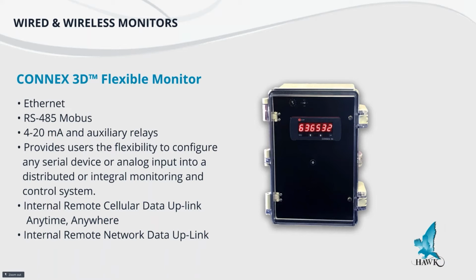That all sounds very technical and sophisticated, but it basically is just a data highway, with Modbus being the language that we communicate within that data highway. It allows us to communicate with many other devices, whether they be 4 to 20 milliamp analog devices, or 0 to 10 volt analog devices, or whether they just connect with on-off auxiliary relays.